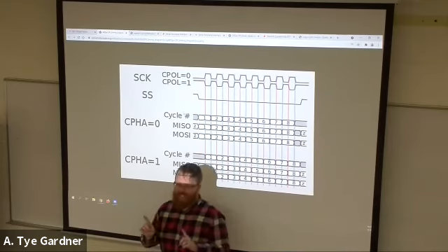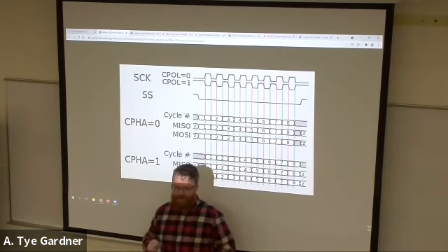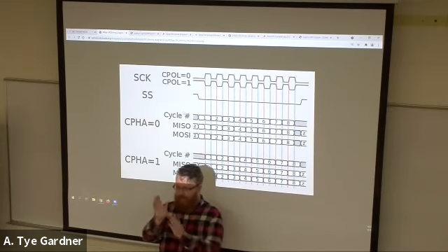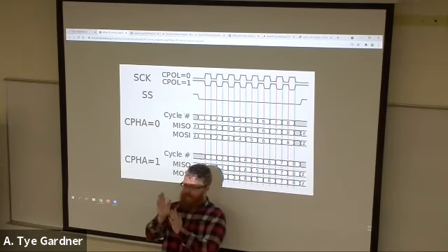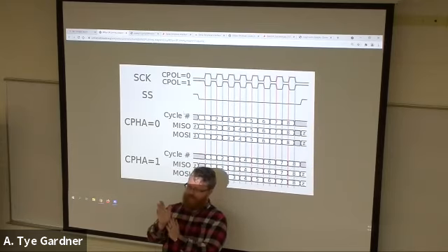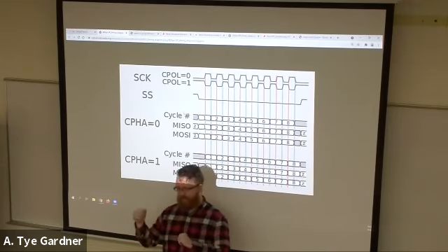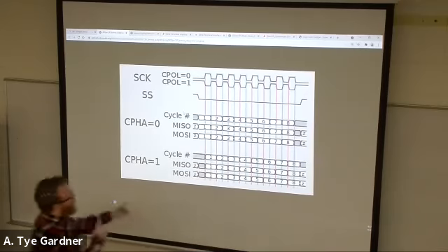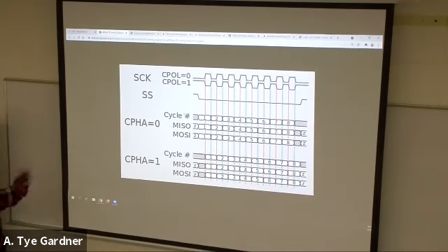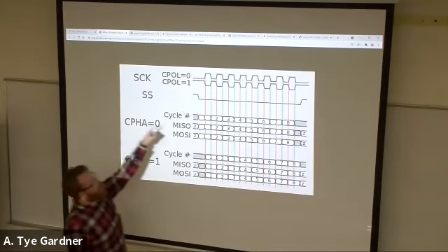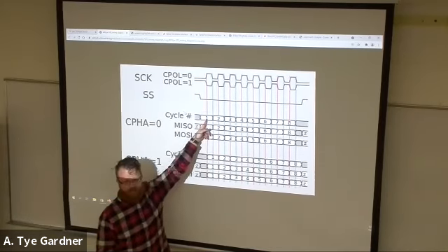But every once in a while, it would go the other way, because the clock placement is not a predictive deterministic location. It's got a probability distribution over a range of which it might jitter. Okay. This is really all you need to know: we have to read this kind of diagram and go, okay, 0,0 means rising edge of clock falls in the middle of bit 1.